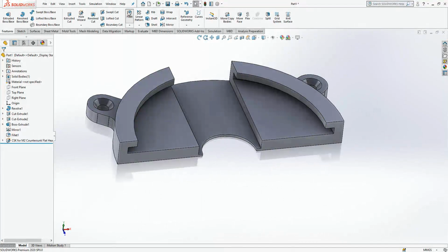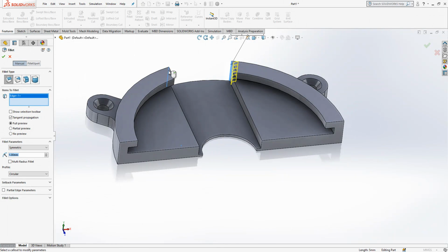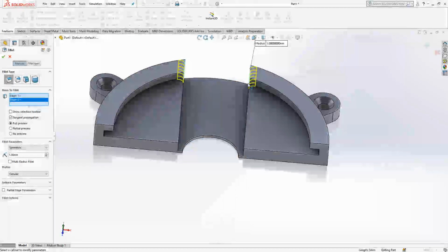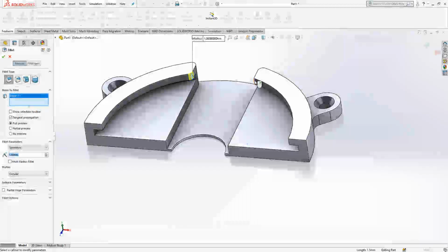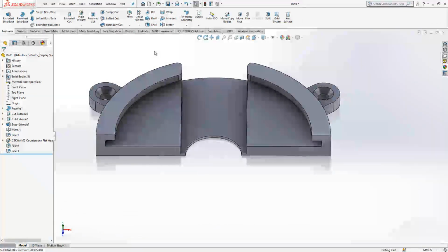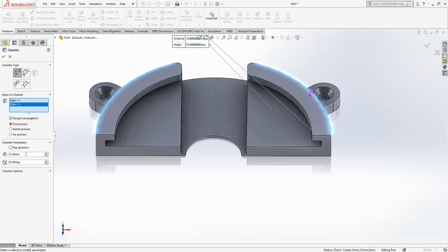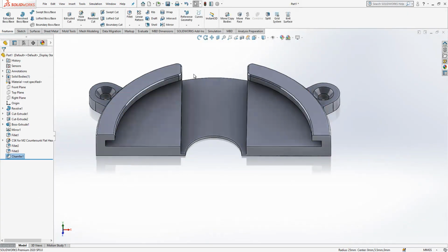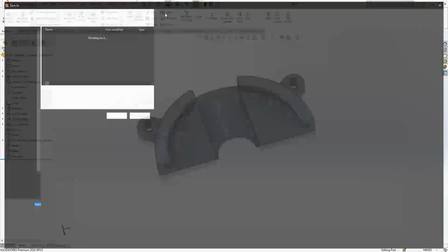Looks good. I select fillet now. Let's make it 1 for these 2 edges, and here another 2 fillet. These are 1. Yeah, we could clean them in one operation, but I didn't think of that at the moment. Anyway, chamfer is selected. We're gonna add here 2 times chamfer along these edges. It will be tangential move. You see something like this. Yeah, it is good. So we can say first part.